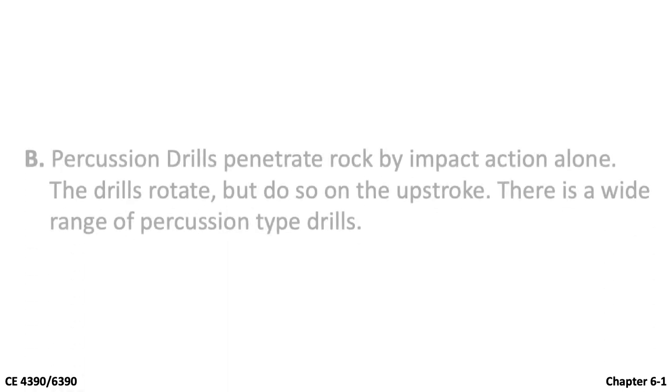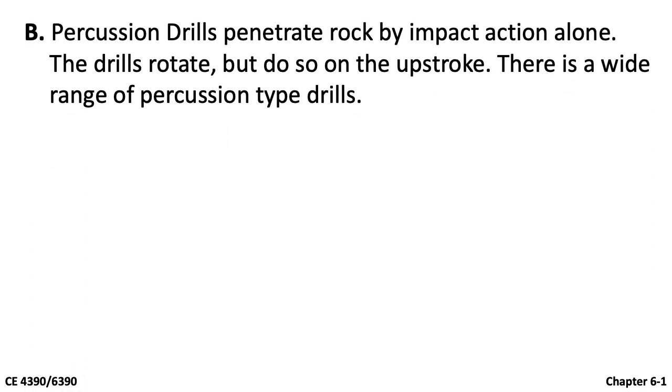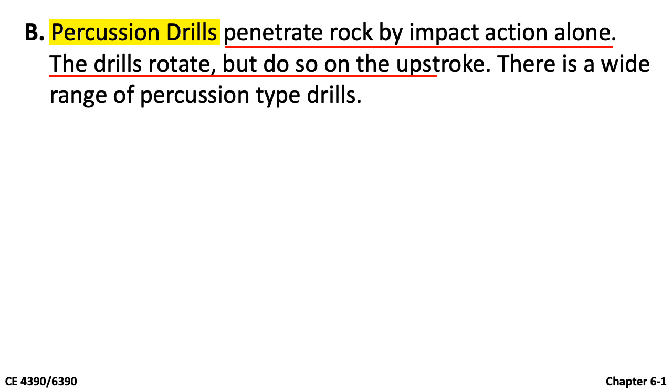First, let's learn about percussion drills. Percussion drills penetrate rock by impact action alone. The bits of these drills rotate to assist in cleaning the hole and to provide a fresh surface for each impact. The rotation is made on the upstroke only, so no cutting is accomplished during rotation.